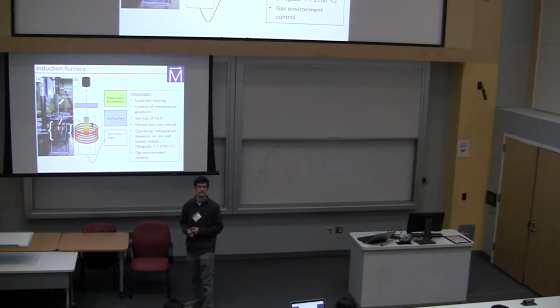We don't want them to oxidize during the growth. So we flow gas through here. You could put it under vacuum if you wanted to. And then we've just capped this thing with water-cooled flanges on the top and the bottom to try to prevent this area from overheating. Incredibly, even when this is at 1700, the quartz itself is not glowing white hot or anything like that.